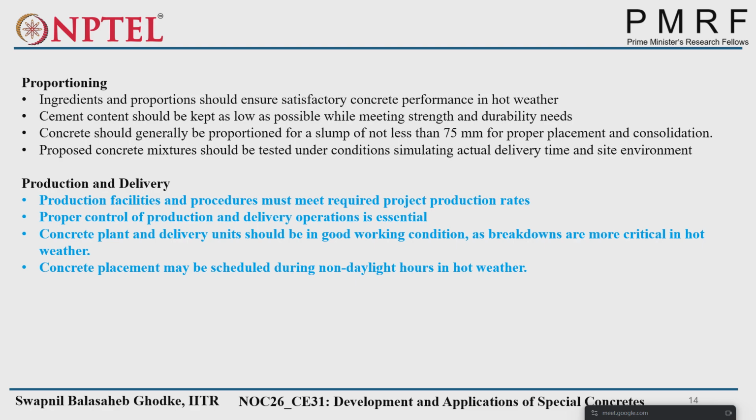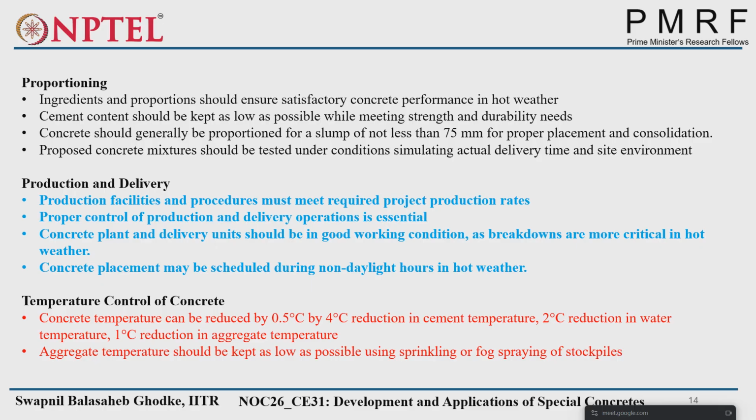Production and delivery should be scheduled during non-daylight hours, depending on the weather and working conditions, and we have to plan for breakdowns. Suppose continuous concreting is there. If it is done in batches, we can break it down, which is more critical in hot weather conditions.